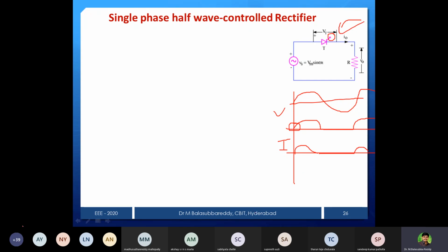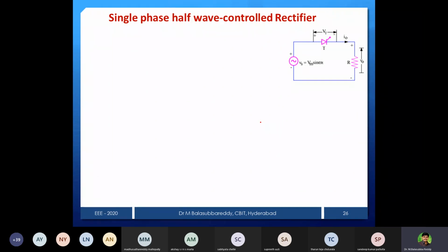That's what diodes and thyristors are exactly similar except for the starting point. Whereas in the diode, the starting point is from 0 onwards. And now for thyristors, even though it is forward biased from 0 onwards, you want to fire the device at a particular instant, so you provide the pulse at that instant. That is the reason you require a firing circuit. That circuit will generate the firing pulse based on your requirement. Suppose I say I want to fire the pulse at an angle of 30 or 40 or 60 or anything, at that instant only it is going to fire. That is the only difference.